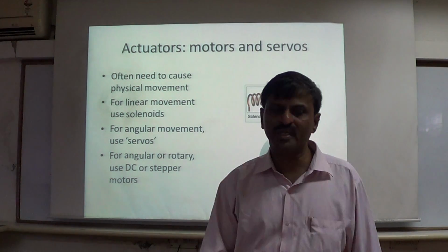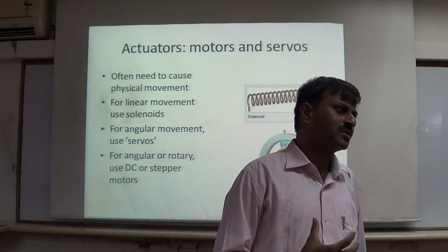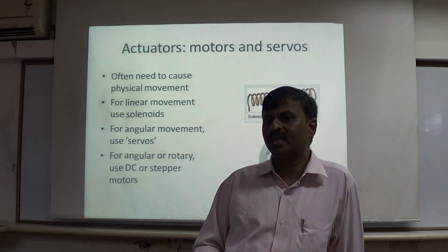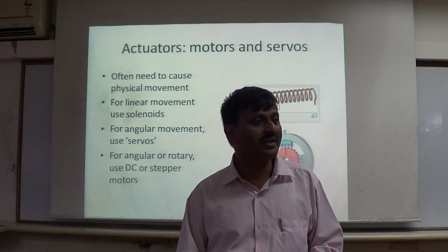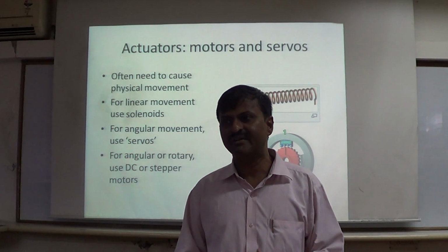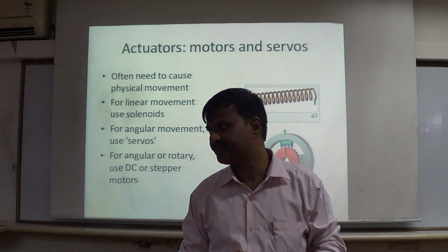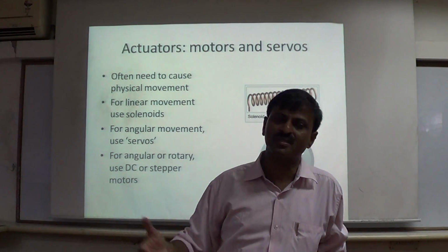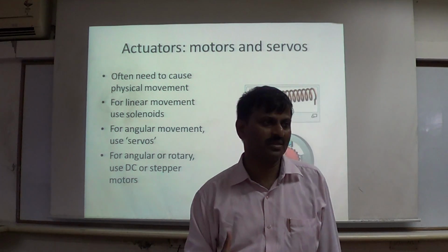Okay, so it's not that we always use DC motors. We also sometimes use solenoid valves. For example, in process control instrumentation, it's not the motors, they are the valves, right? A robot is not necessarily always controlled by DC motors or stepper motors. They are also controlled by pneumatic and hydraulic control systems. For example, in four-wheeler manufacturing facilities, if they are lifting tons of weight, they are all hydraulically or pneumatically controlled machines. The motor is not lifting that weight. In a hydraulic control system, some oil will be compressed, then it will expand, right? Hydraulic control systems or pneumatic control systems.